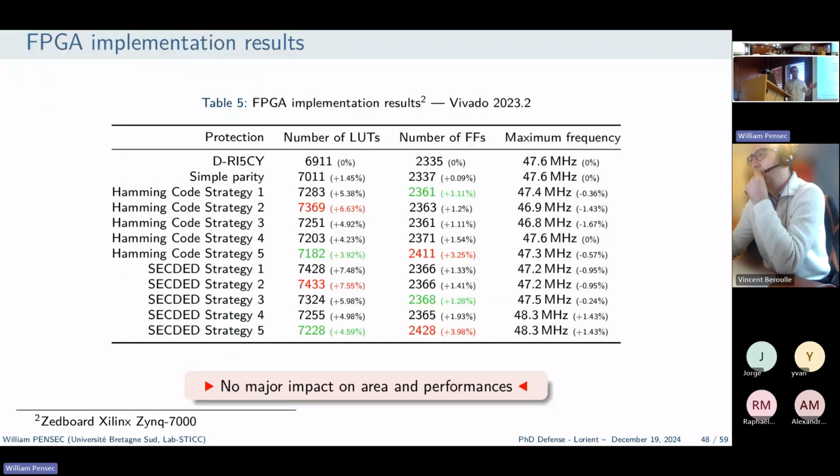Yes, of course. For example, when the application is running, the DFT will detect the attack. In the buffer overflow use case, there is a signal that I showed in the figure previously. If you consider this signal as a trigger, you can detect the moment when the exception is raised, or even consider the propagation of the tag. You can trigger when the tag is propagated and inject a fault from this trigger. But you would have to first evaluate this execution on a board, for example, to evaluate at which moment you have to inject the fault. You mean with side channel observation?